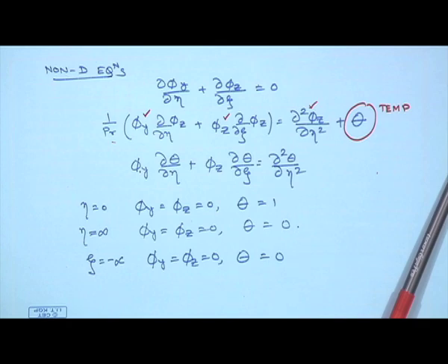That is the assumption that we are making. Since free convection flow is characterized by slow upward movement of the fluid, we do not expect the effect of convection to be significant on the final solution of the problem. We are not saying it is 0 as in the case of creeping flow, but we are saying its effect is going to be small.